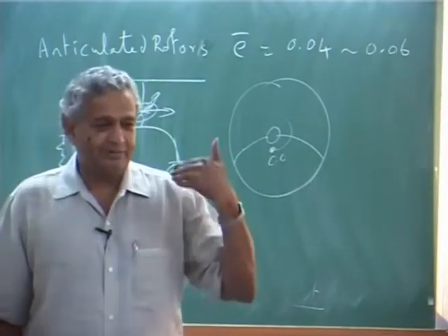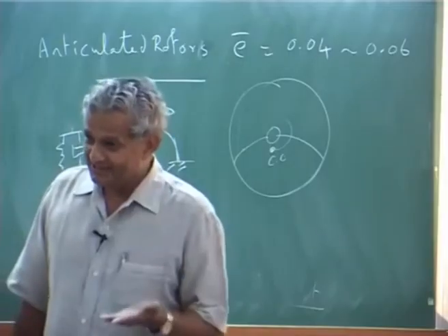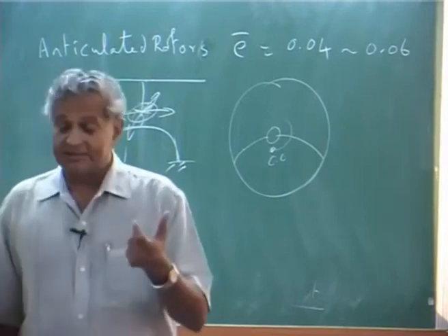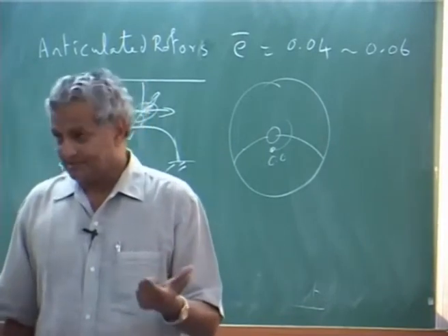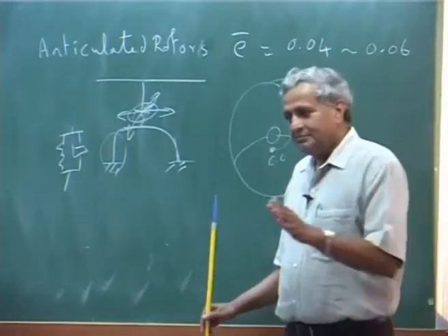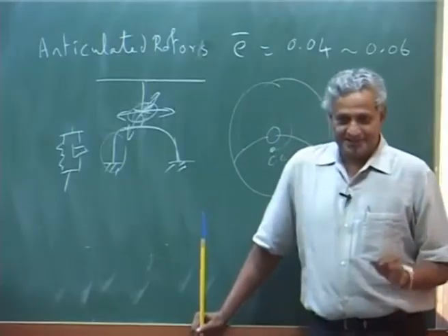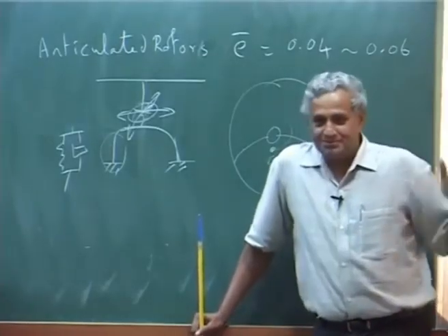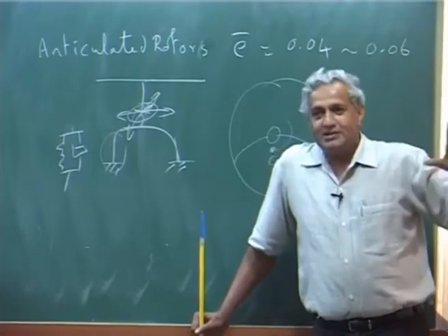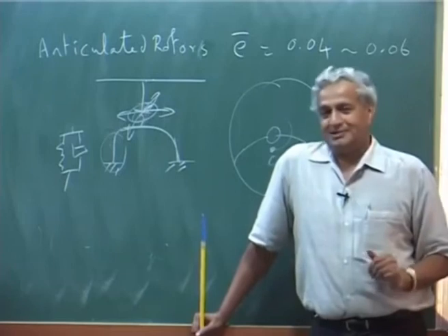Okay. And the damper you put, but again please understand, if you simply say okay, put a damper, then its weight, cost, maintenance, everything gets added, and that becomes a very critical component. It is not that it is non-critical. That is why, if you want to know the importance of lead lag dynamics of the blade, it is not in isolated lag dynamics, it is actually in combination with other modes that the importance comes out.